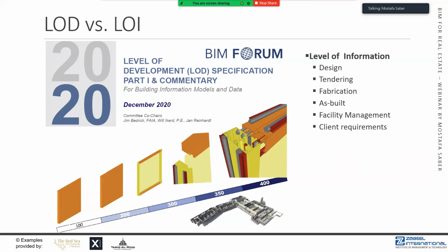However, if you ask for specific information requirements, you'll be able to specify who is the manufacturer, for example, for this element, or what is the U value rating for this element. If we're talking about a window or a wall, what is the actual material used here? And what is the thermal transmittance value for this building component? Does it affect our energy analysis? Does it comply with authority regulation? All this is information that could be easily extracted from the model only if you request it.